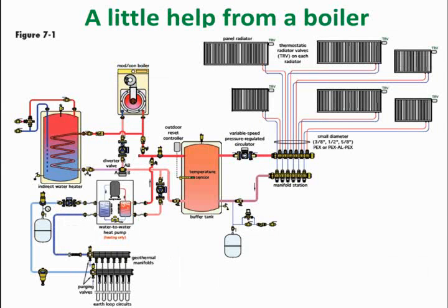All right, now there might be an application where you've got a geosystem that's going to need a little help sometimes. Maybe this heat pump wasn't sized to handle the load under severe conditions, or it was purposely sized so there would be a boiler supplement or addition to it. So here we're showing just taking a little ModCon boiler, maybe a Lochinvar Knight or whatever brand you'd like, tied into the system.